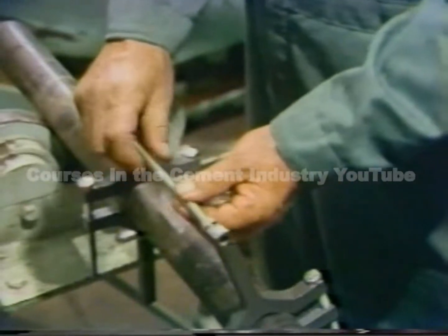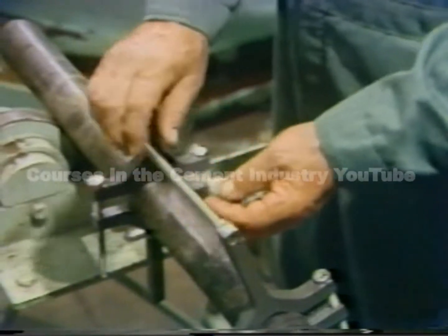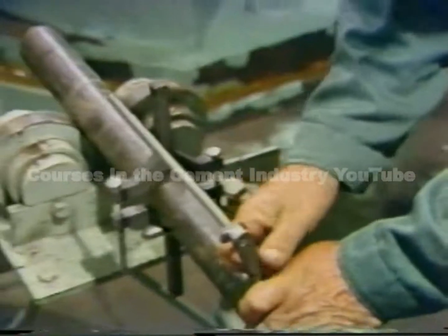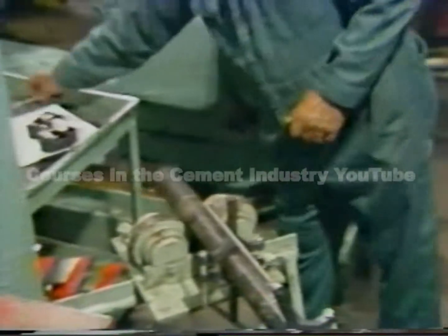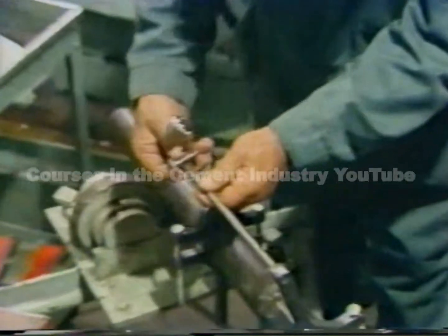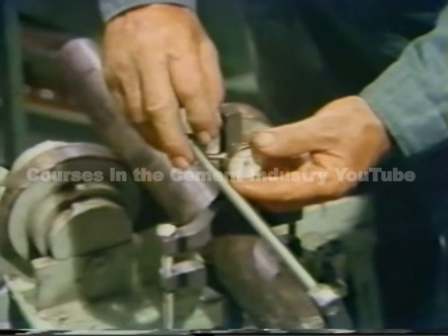As you can see, it screws into the bracket. Then it's locked into position with a lock nut. The more rigid the mounting, the less sag you'll have, so make sure all fittings are good and tight. Now the first dial indicator can be installed. This one will be used to measure angular misalignment, so it's mounted against the face of the post.